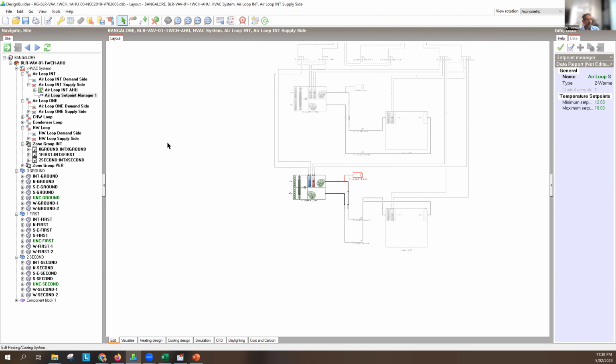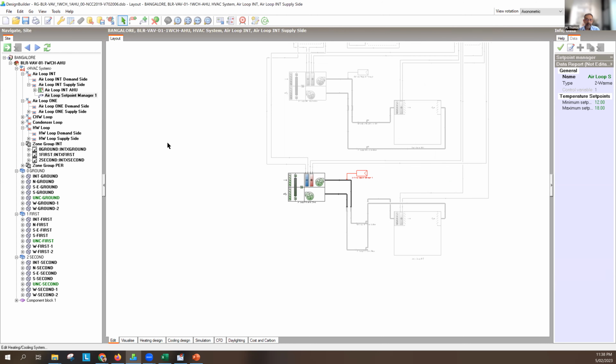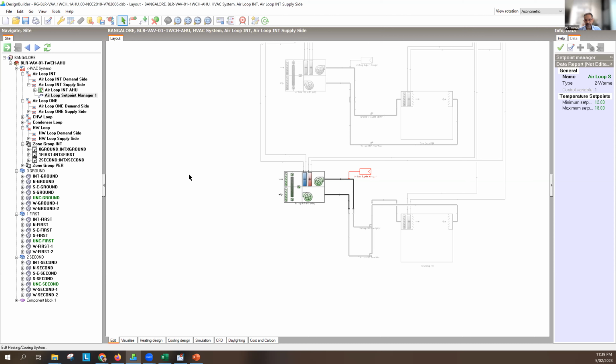You can do many different kinds of systems. I think in the video, they actually talk about radiant panels. So they talk about both heating and cooling radiant panels. The way that you model them in Energy Plus and Design Builder is you also have to look at the construction because it kind of assumes that your radiant surface is either your ceiling or your floor, and you have to change that as well. And there's a little bit of an explanation on that, okay?